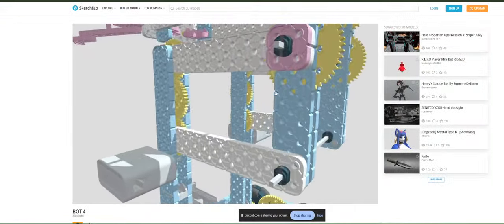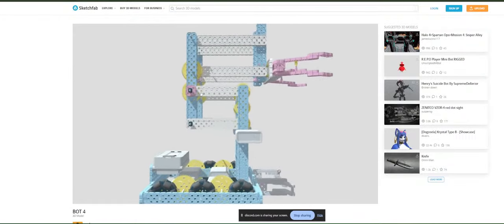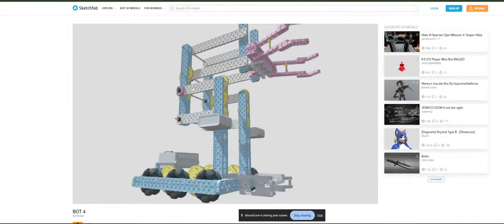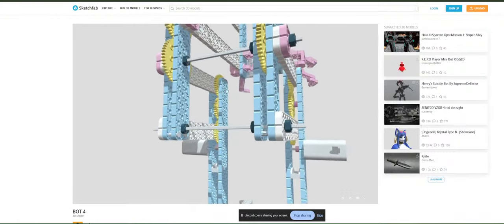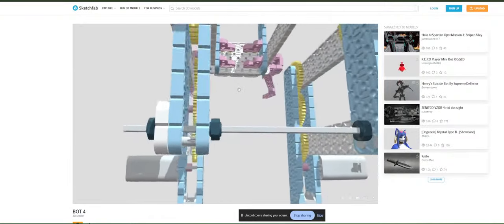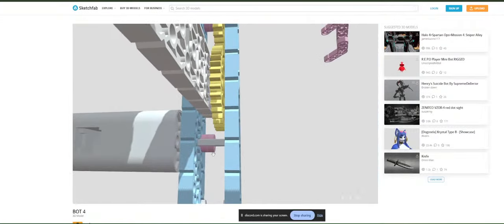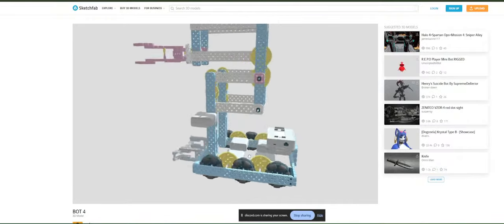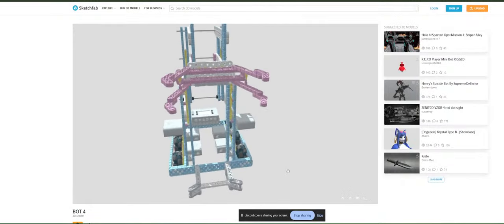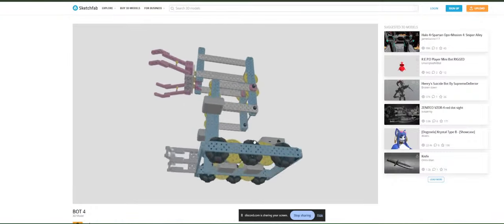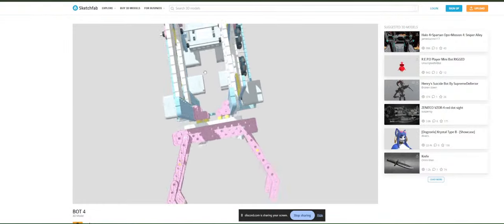Yeah, I basically just based this off my actual robot that I built, so I just copied it mostly. I put the motors right there because it was a very 24-hour build robot. Once we got access to a library with double reverse 4-bar, we copied it and put a 4-motor drive on it because we knew it would be very helpful for maneuvering around the field. 3-to-1 gear ratio on the double reverse 4-bar. I don't think it's meta, but that was my first time CADing, so I had fun. Pretty good first CAD. I didn't know how to use pneumatics and stuff, but it was really good. Only China appears to know how to use pneumatics in CAD right now, and some talented people.